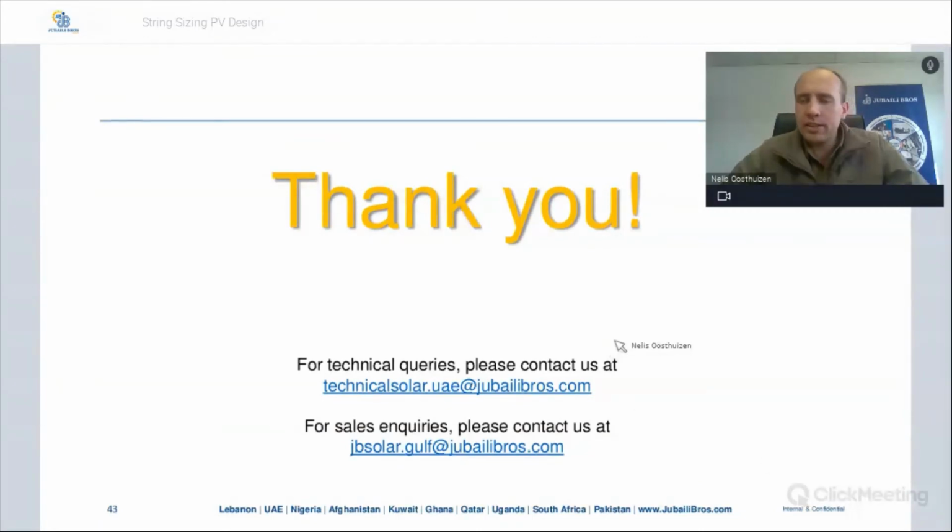Right. So that's it for today's presentation. I think a lot of it is really useful if you're using computer-aided simulation software, where it's assisting you with the string sizing and design. But then we also do have offline options available with the Huawei string sizing tool. Or if you want to go back to the old school way of calculating everything by hand, you now know how to use this formula.